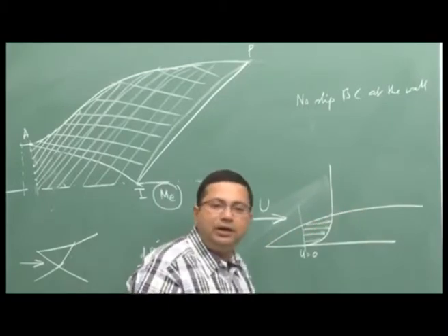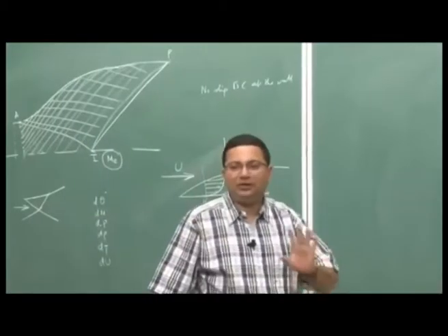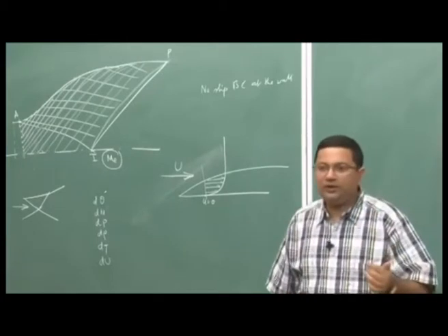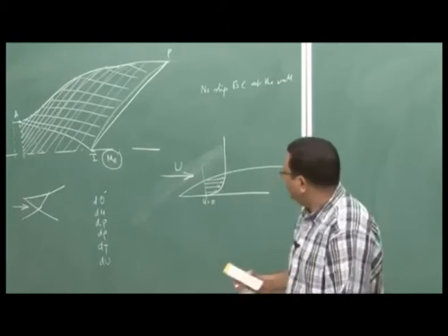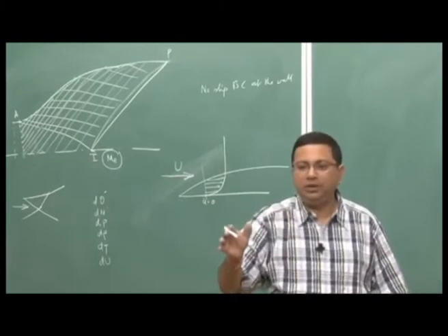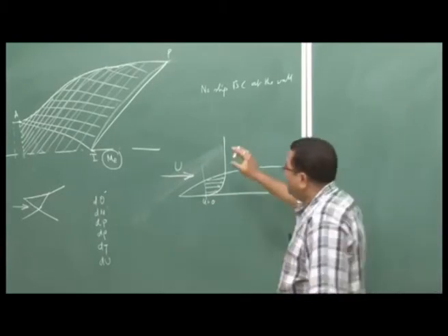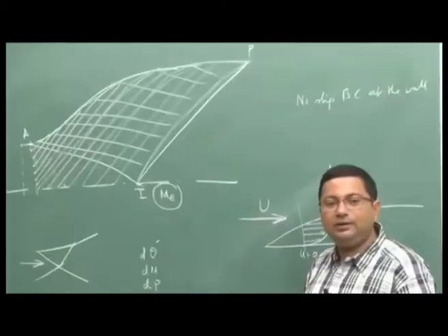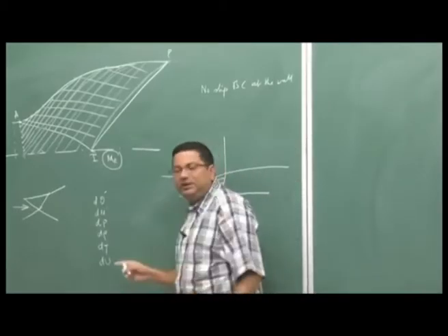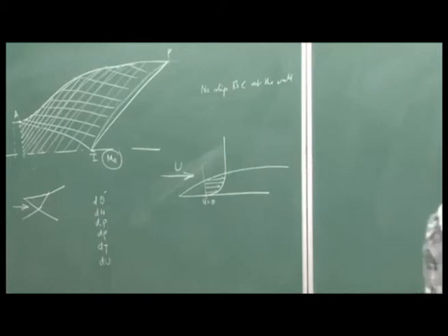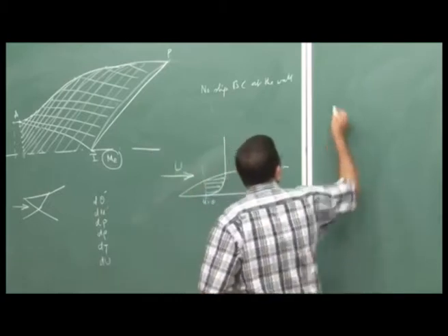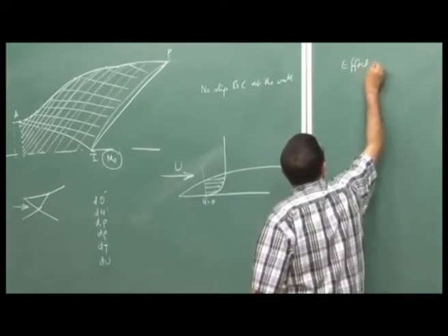Essentially, by not considering the boundary layer, we have completely eliminated the skin friction losses, but I have said in the previous lectures that the losses are because of skin friction as well as because of the 3D effect. When we went from one dimensional flow to multidimensional flow, there were some losses; that will be eliminated by using this method, but it does not even consider the skin friction losses. Therefore, skin friction is something that needs to be addressed. So, let us now first start from addressing the skin friction. Let us look at the effect of friction.